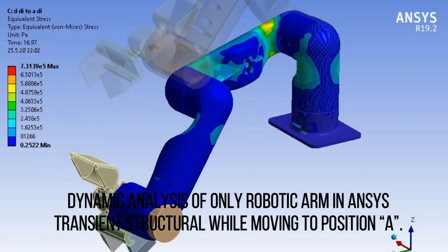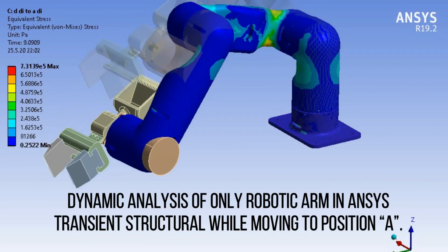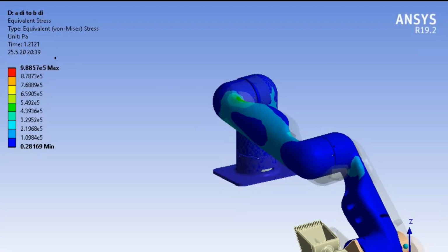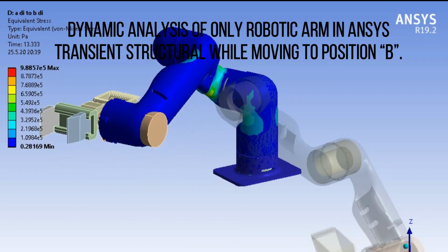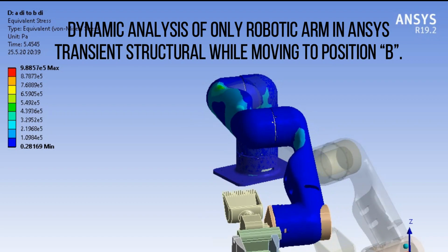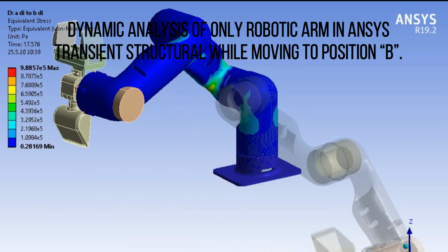The analysis was carried out using the arm as shown over a period of 20 seconds under the influence of gravity. Here this shows the dynamic analysis of the robotic arm in ANSYS while moving to position B. The maximum values of stress reached during the arm motion are 0.73 megapascals and 0.9 megapascals, which are far less than 40 megapascals, the tensile strength of ABS plastic.